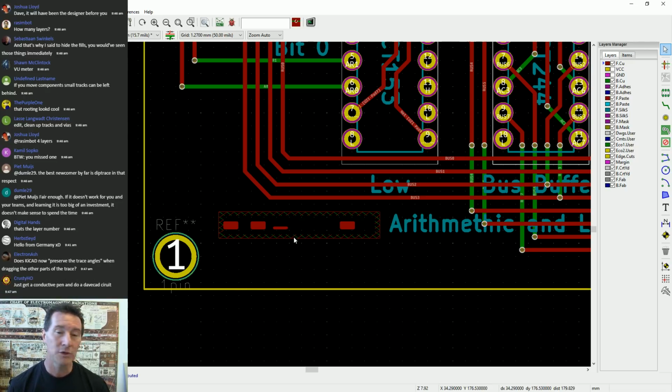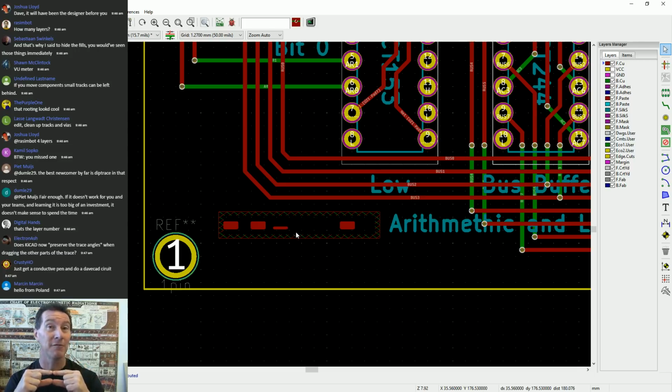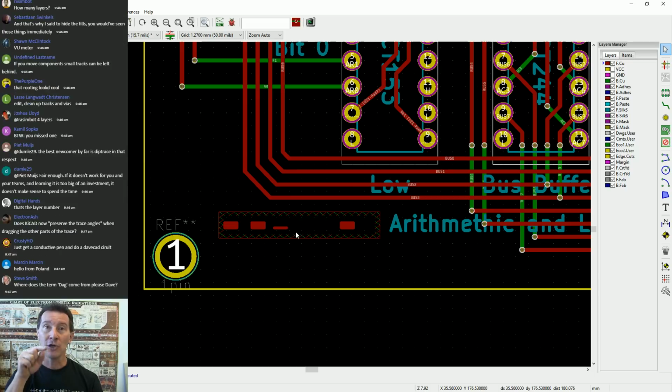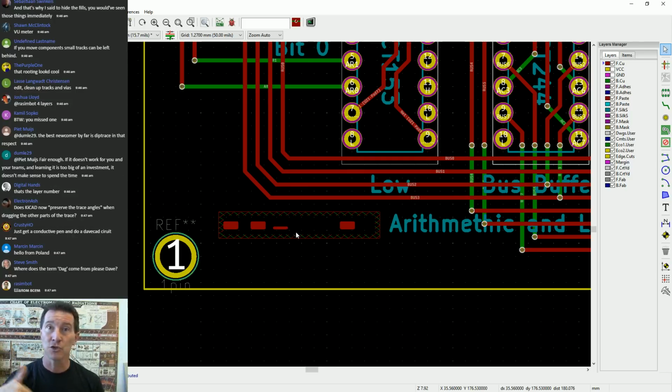And what you do that for is that when you get the board back from the manufacturer, you can look at the test coupon, and it's got all of the information in there you need to check the manufacturing quality of that board. So you put it under the microscope and have a look, and you can see the alignment of the layers. You might pull back your copper there so you can see through the different layers, and you can see the alignment of the masks and everything, solder mask, your silkscreen top and bottom, your copper, stuff like that.